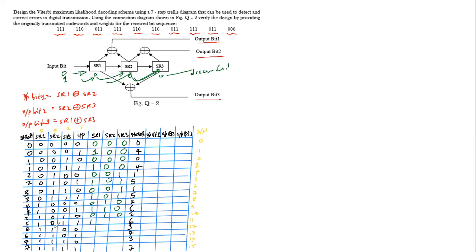And we feed this with a 1, so that's 1, 0. Feed this with a 0, so that's 1, 1. And I feed this with a 1, so that's going to be 1, 1 here. Then feed this with a 0, then these are shifted. That's 1. Then we feed this with a 1, then that's shifted, and the last one here is discarded. So is this clear? We've populated the table.